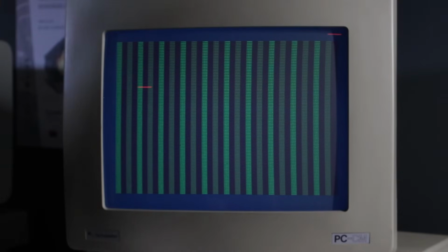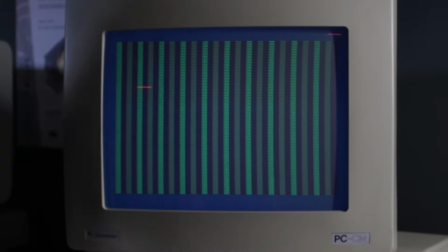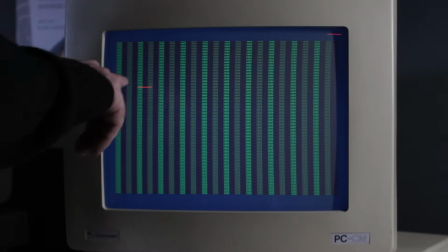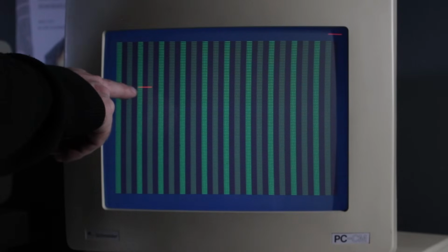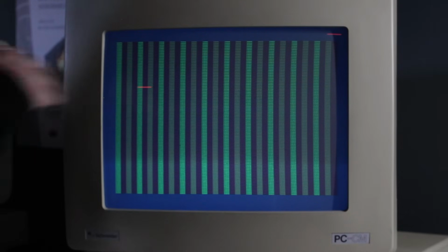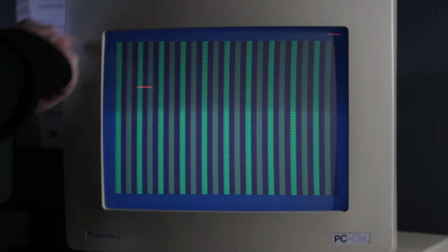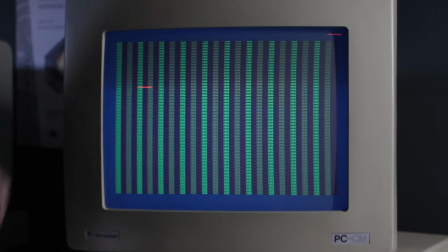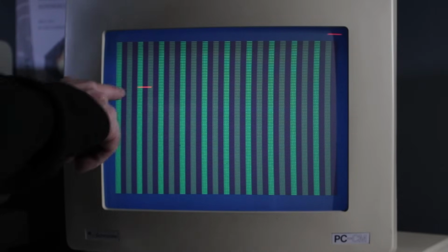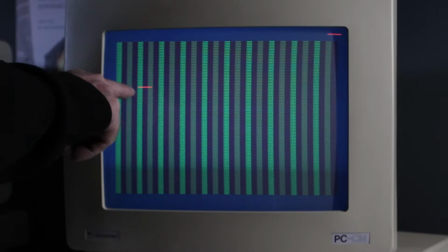Well guys, I've done it. I got it to fire every frame at exactly the same time using the programmable interval timer rather than counting out CPU cycles. And the programmable interval timer is on the same crystal as the graphics chip, so there's no problem getting it to fire off an interrupt at exactly the same place every frame. In fact, it's exactly 19,912 PIT cycles per CRTC frame.